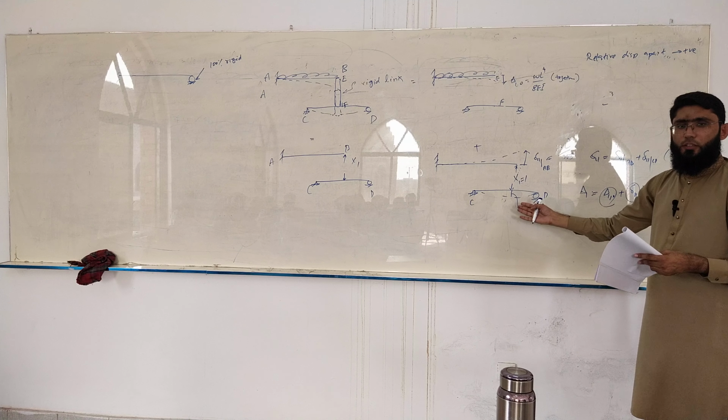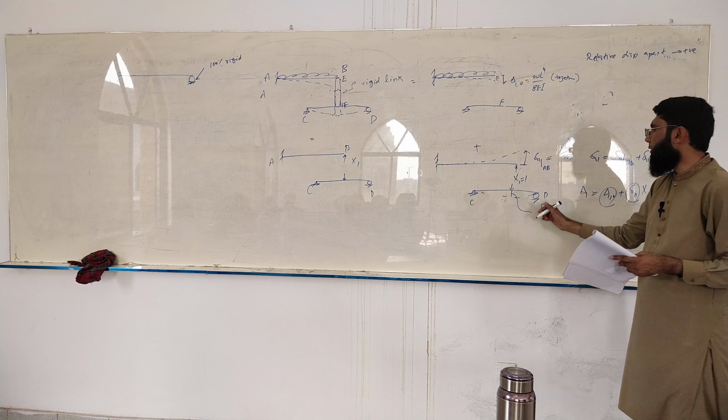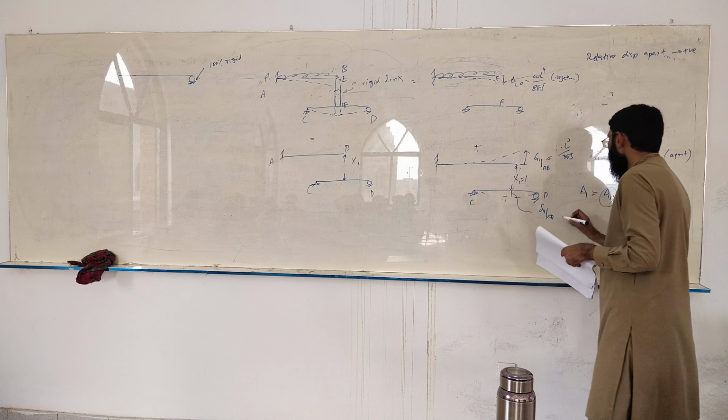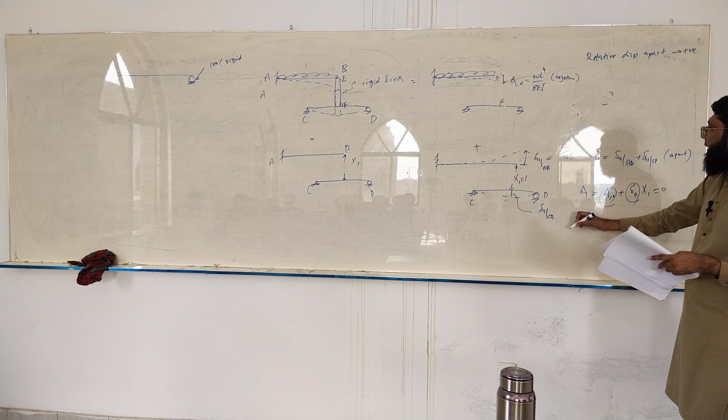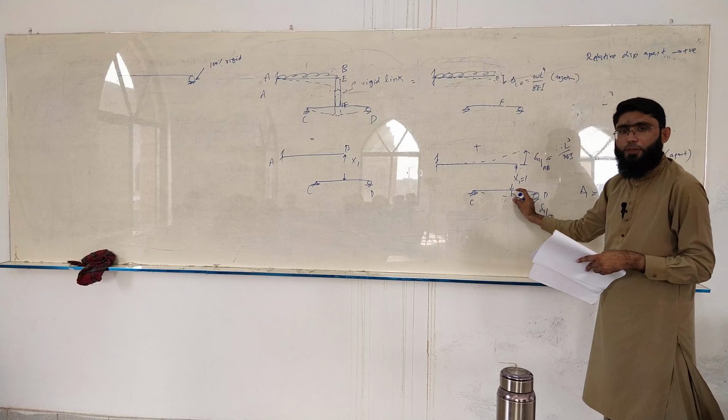And what about this case? You could work out this part, but we could simply call it the displacement due to a unit load. So what could you call it? Flexibility. Delta CD may be called the flexibility of this beam under this condition, load and displacement at the same point. I could say that it is equal to 1 over K CD, the reciprocal of stiffness.